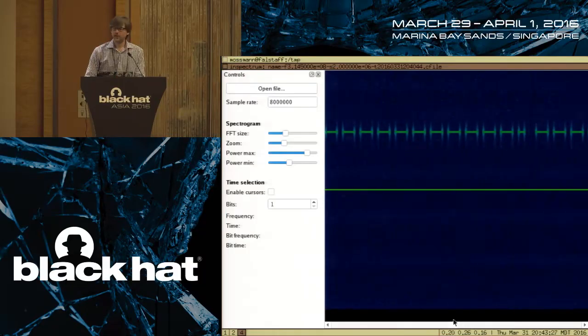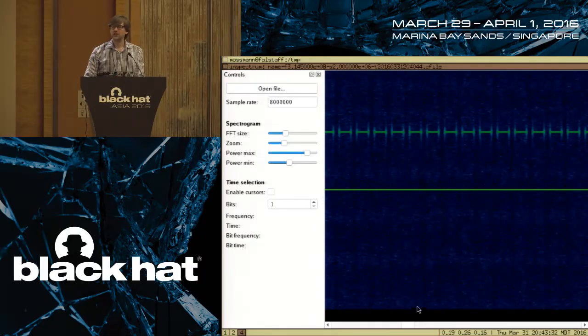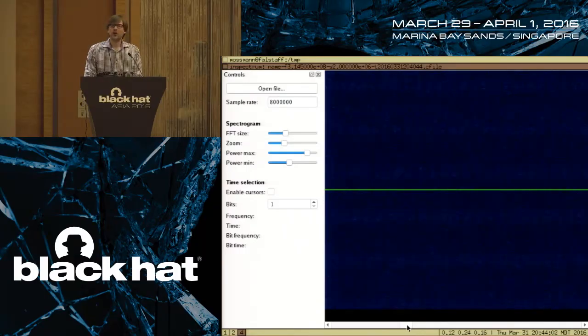Every single pulse is at the same frequency, which tells me this is not a frequency modulation. But the amplitude changes. The amplitude is represented by the color. The color goes from this blue background color to this green color when there's an active signal. It abruptly turns on and off. So this modulation I can easily identify visually as being on-off keying, which is the extreme form of AM. It's turning the amplitude of the radio transmitter on or off. And I can also tell that it's made up of these distinct pulses.